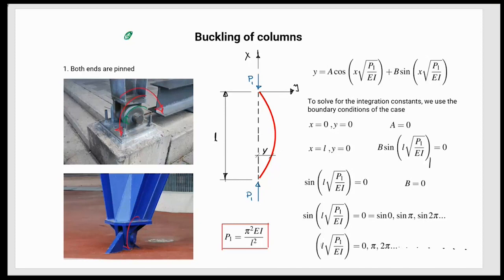The same here. This is able to rotate to this end or this other, if the upper part is cut. This is a freedom of rotation. It cannot have a moment because it is free to rotate. Then there is no moment appearing here when I do this free body diagram. The same happens at the bottom.